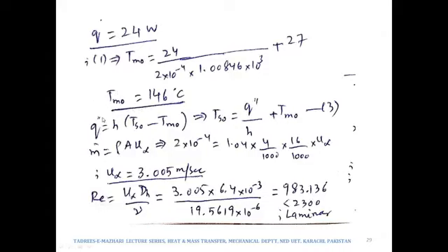Right? Now, in order to calculate Ts naught or Tw naught, the surface temperature at the pipe outlet, at the pipe exit, we would be using h times A times delta T, where Ts naught is the only unknown in this expression besides h.